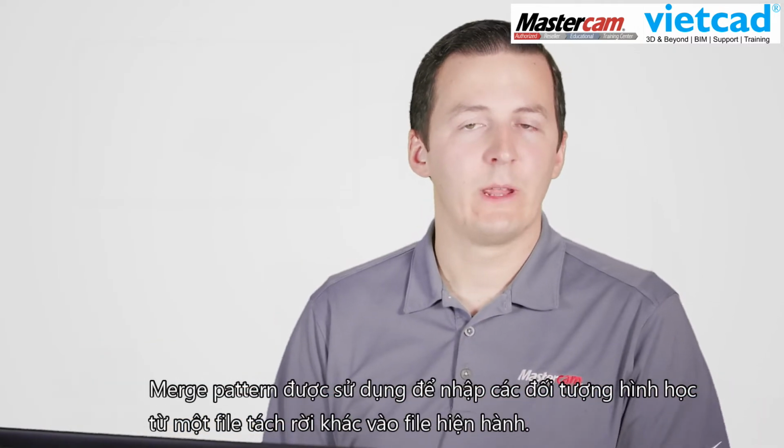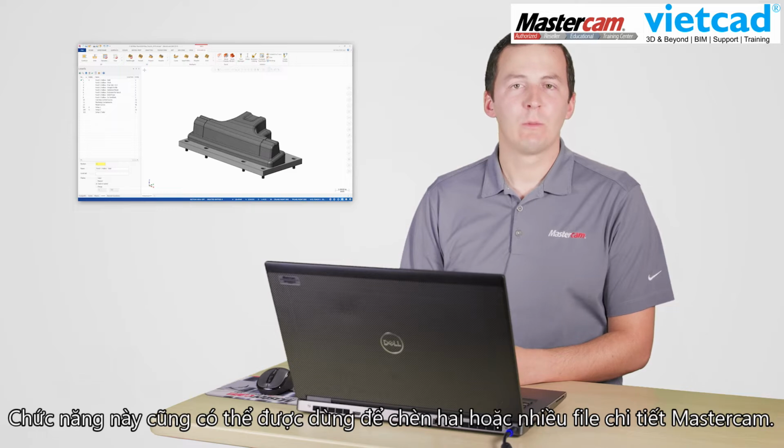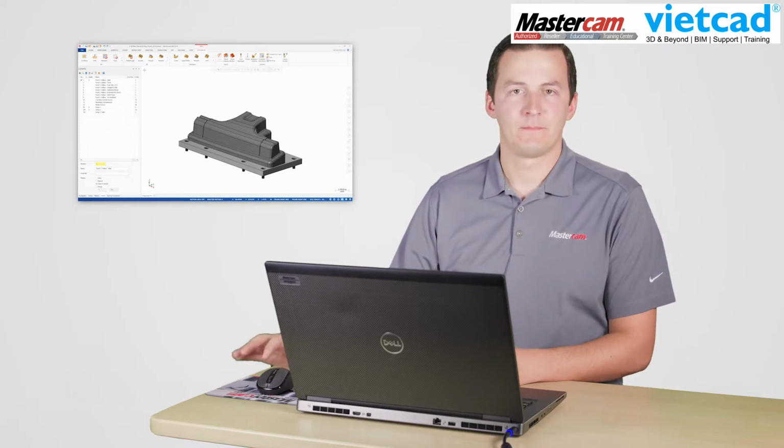I want to show you some of the new options within the Merge Pattern functionality of Mastercam 2020. Merge Pattern is used to import geometry from a separate file into your current Mastercam part file. This can be used to merge 2 or more Mastercam part files as well.